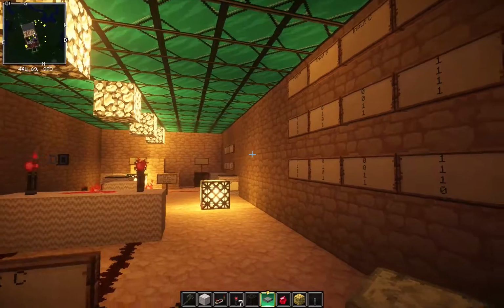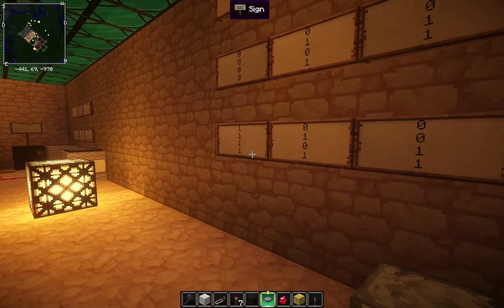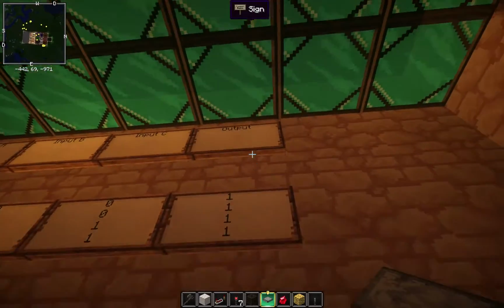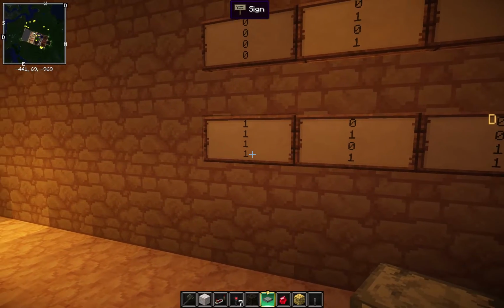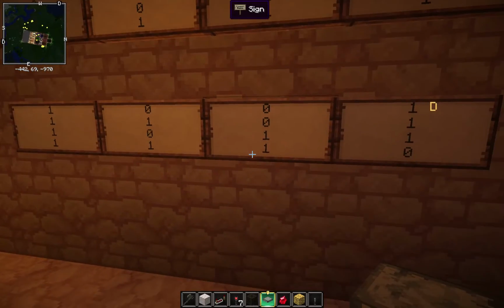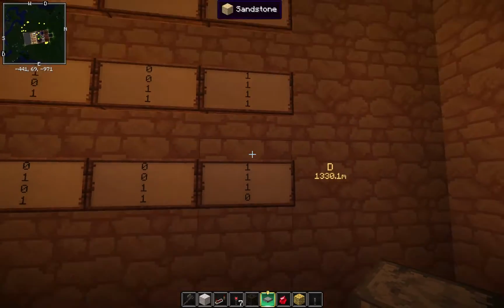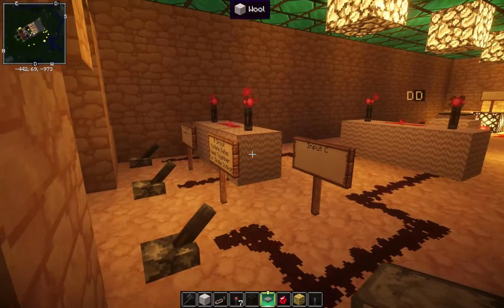And so we can tell that this is pretty much just two AND gates. We want to have this and this and this to make the change to the output. Any other combination that does not have input A and input B and input C on at the same time does not change the output from its normal base state. So let's test that out.